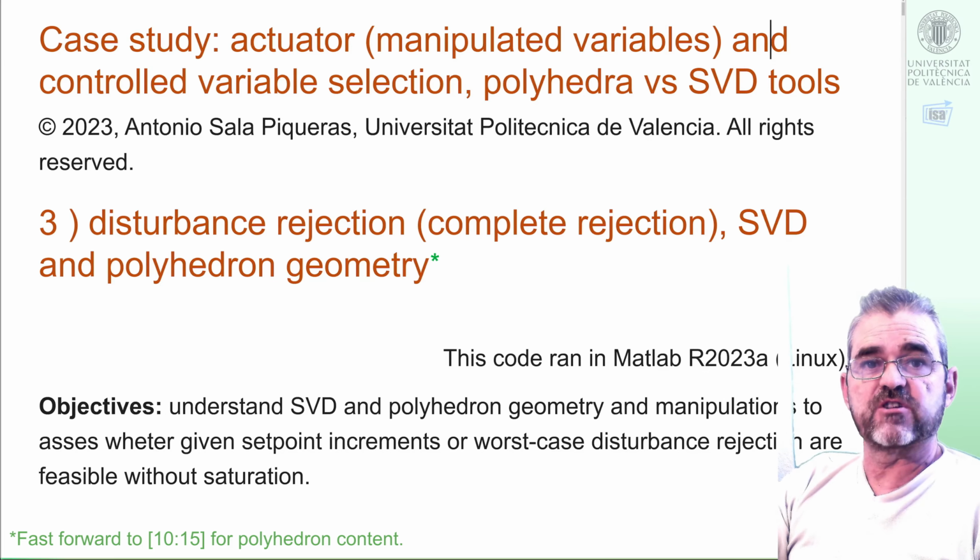But okay, as we chose this output scaling matrix in our setpoint tracking discussions, we'll just keep the same output scaling, because in such a way the scaled gain from manipulated variables to controlled variables will be exactly the same that we already computed and discussed in previous videos. But again, the choice of output scaling is not relevant because we do want output increments to be 0, so 0 can be scaled by anything and it's still 0.